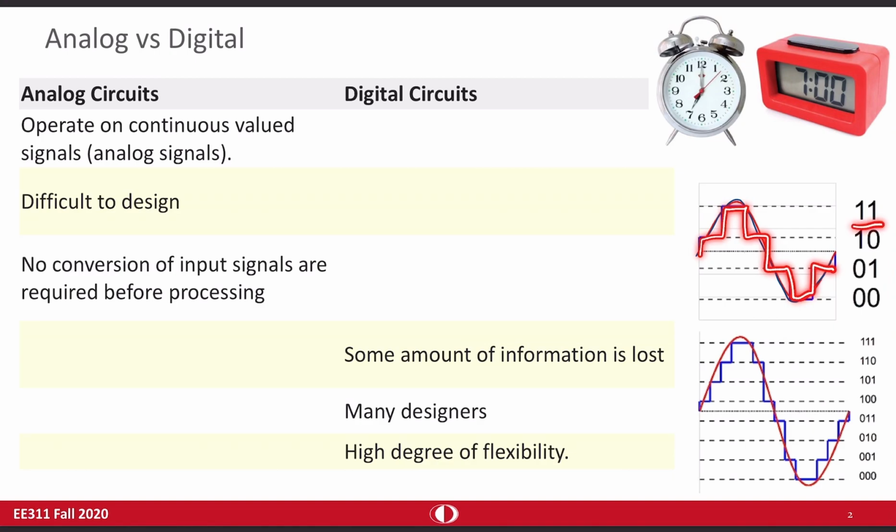Of course, it doesn't look like the original signal because you are losing some data. And by increasing the number of bits in here, by increasing the resolution, you will have more steps. Like for this 3-bit version, you have more steps, and because of that, the output digital signal or discretized signal looks much more like the original analog signal, the sine wave. If you use, for example, 12 bits in here, you wouldn't recognize the difference between the blue one and the red one because with the bare eye, it is very difficult to notice the difference between the step heights.